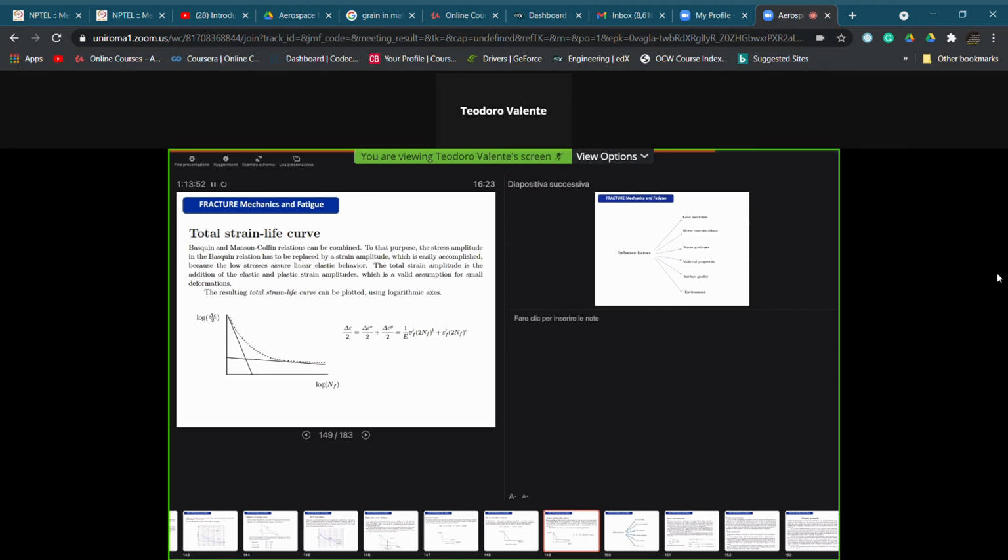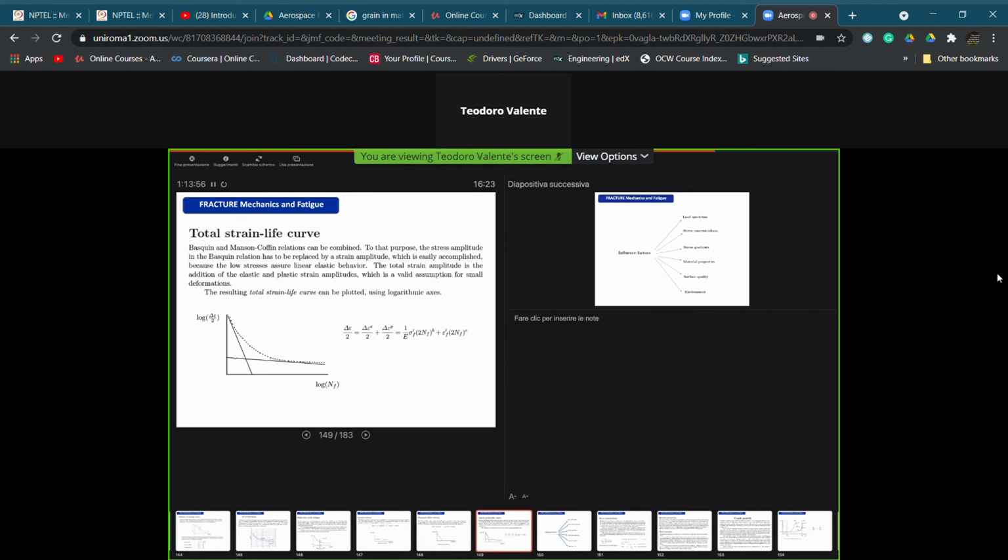Then we can have some cases in which for a certain period of time the system is going to be stressed according to an HCF model. For other periods of time, for example overloads, even short, we can have the necessity to apply on a macro scale the LCF model. And in this case, when we need to take into consideration both for their relative period of time,